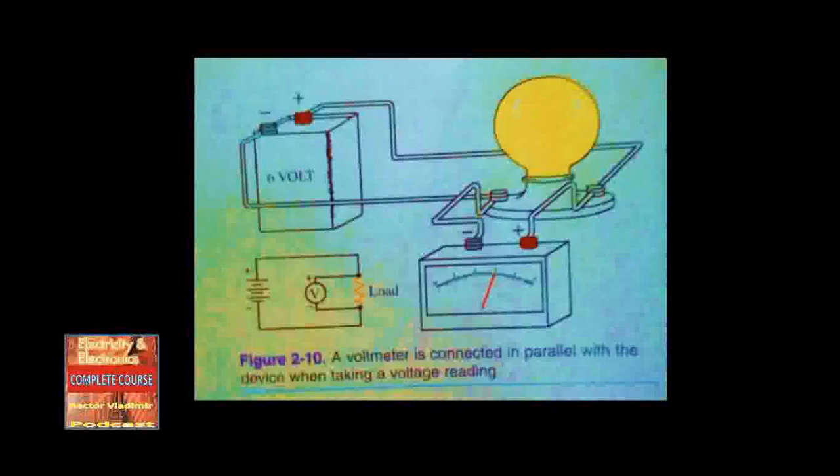2.3 Voltmeter. The same basic meter movement that is used in an ammeter is also used to measure voltage. This is providing that the impressed voltage across the coil never exceeds 0.1 volts, the same as computed for full-scale deflection. This is important, always as computed for full-scale deflection.